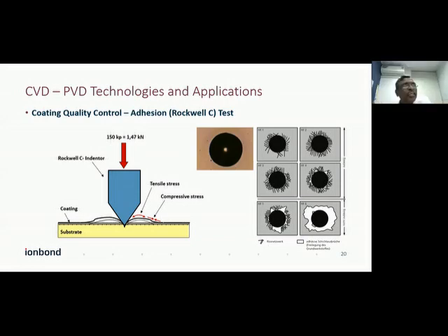Basically, sir, Teflon coating is not done in vacuum, so it is atmospheric pressure. That is the first, and it just acts as a non-sticking one. So it doesn't have the hardness. So from the wear properties point of view, it doesn't work. It wears so fast.